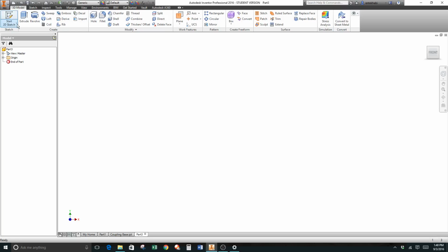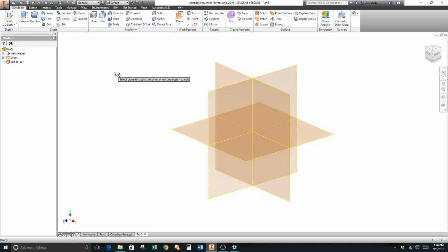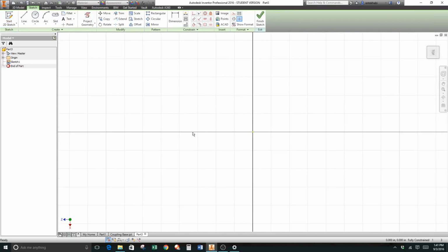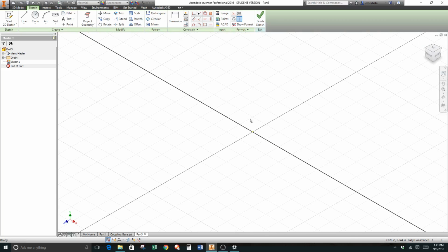Let's begin with the 2D sketch and then select the plane. In this particular case, I'm going to choose the XZ plane for the best orientation, and we left click on that. It's always a good idea, notice here my icon is shown upside down, to switch back to the isometric view. There's a home navigation tool that we have been using. Select that, and that gives us better orientation of our model, so we know we are in